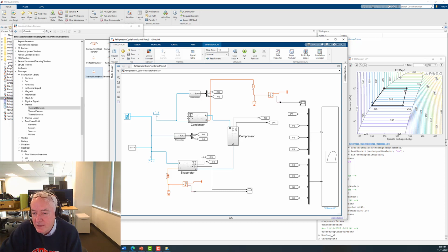He also explained that you really don't need to be operating right on the edge on your fluid entry here, and in fact you shouldn't be. So we're going to move this point a little bit more to the middle. It comes down to charging the refrigerant system with what he calls the correct density of refrigerant. What that means is you don't want it pure liquid, and you don't want it pure vapor.